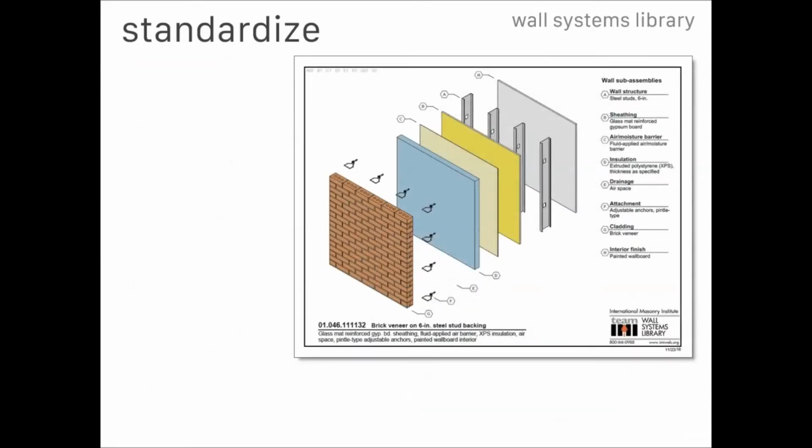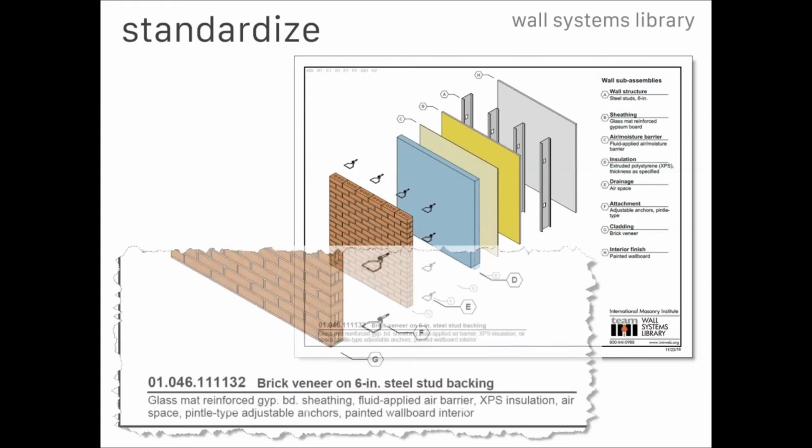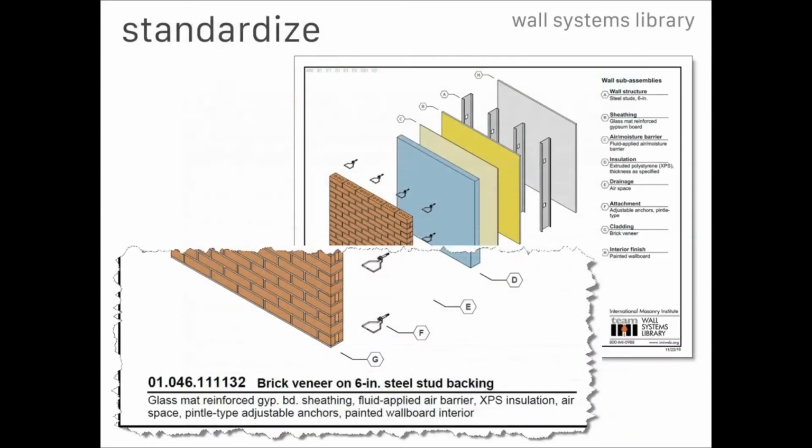And then tier 3, the longer string of numbers, is going to communicate the insulation, the air and moisture barrier, and the method of attachment. And again, we only have attachment in the case of an anchored veneer. There may be a physical anchor or a wall tie. In the adhered veneer example, the attachment would be a bond coat of mortar that may or may not have lath reinforcement or wire mesh reinforcement. So that's what we're defining as attachment for adhered. Single-wythe, there's no cladding, so therefore there's no need for attachment.